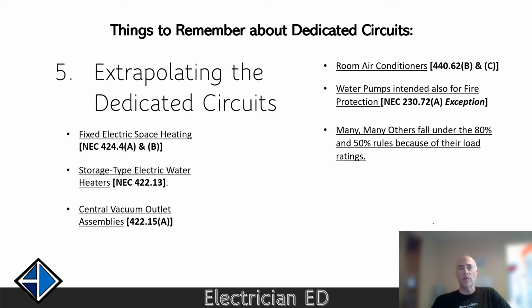Okay, and then there's also, I've already flipped to this part on the slide, but there are many, many others that, by using these rules, the 80% rule or the 50% rule, because of their load ratings, will need dedicated circuits. But I've just shown you how to figure that out, even if they're not named in the code. If you have the breaker space, keep in mind that you're always welcome to put it on a dedicated circuit.